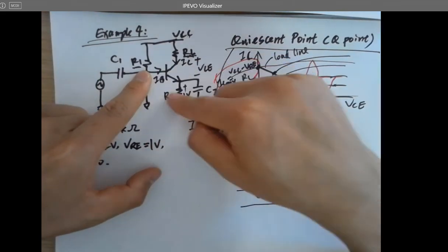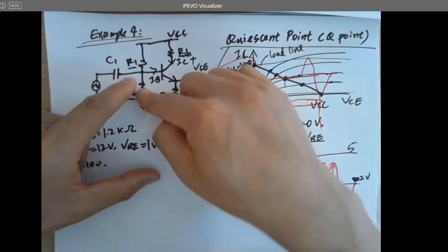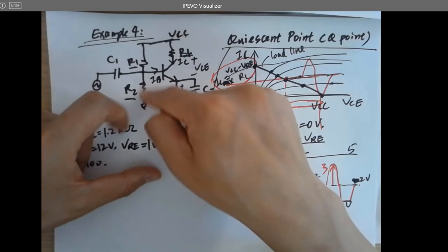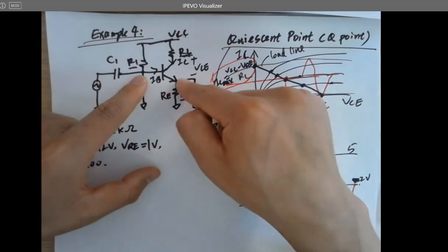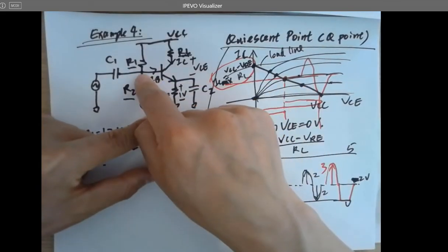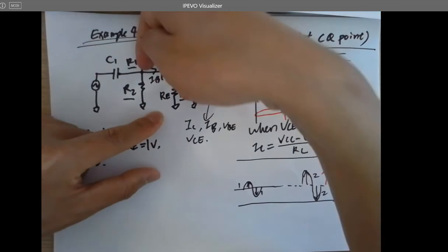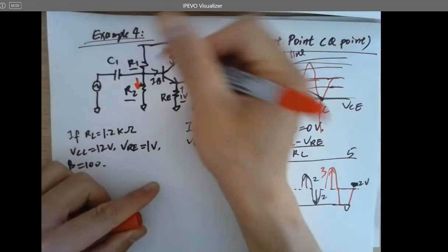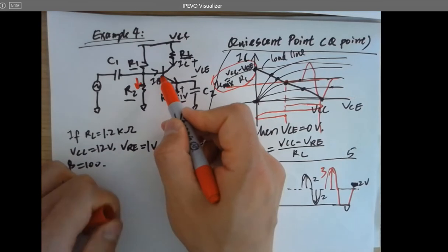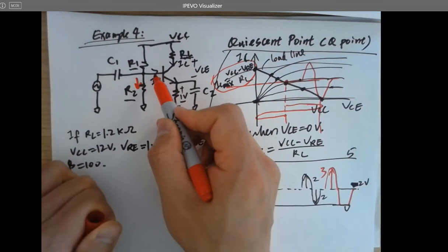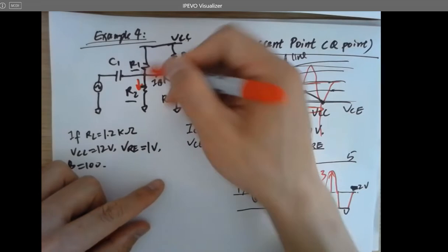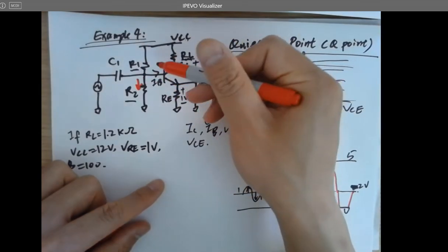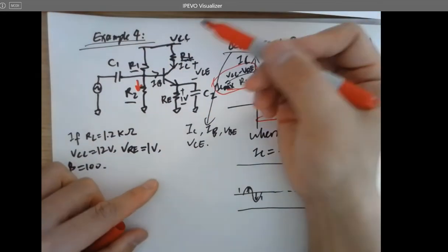If the current flowing here and the current into the base are comparable, then whenever the base current changes, you get a different voltage value here. So you want to keep this robust, and keep the current through here a lot higher than IB. IB will be a tiny current change, but this current is huge, so when IB changes it doesn't affect this too much. So you can bias this transistor to a reliable point.